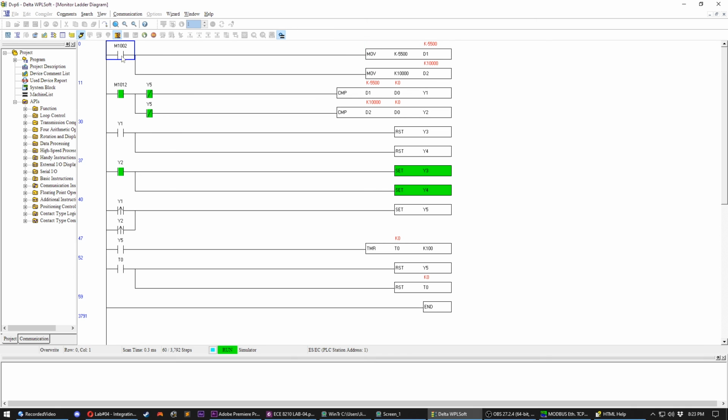But anyway, we can see on the first cycle, these two registers get loaded. And we're doing a comparison every 100 milliseconds, as you can see. This comparison is returning true, which is setting these two values. Anyway, just like I explained it. So let's stop and restart. Now you can see, because we made a change, the timer is going up, and we're locked out of the comparators. Once this reaches 100, right now, the comparators are back online, and the system is reset and ready to go again.